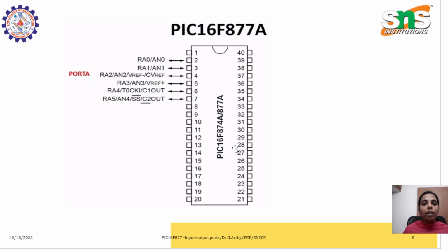As I already said, totally 5 ports are available with PIC16F877A or PIC16F877. Both have 5 ports, and altogether 33 IO signals or pins are available. Out of the 33, port A holds 6 pins, that is RA0, RA1 to RA5, which have pin number 2 to 7 respectively.